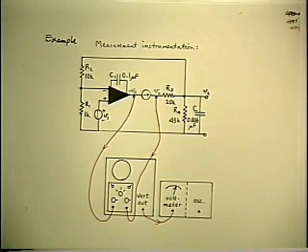So when you think of other ways to do it, there's various more fundamental ways, such as displaying both of the waveforms on a scope, dual trace scope, making sure that you trigger off only one of them, and then observing the relative horizontal position, which you can then use to determine the relative phase angle. That's all right in principle, but it only works in practice if both of the waveforms are nice and big and well out of the noise.